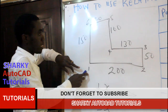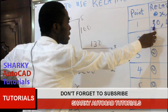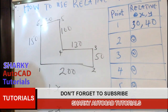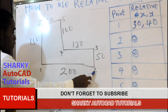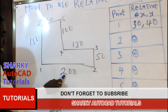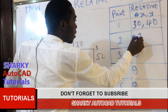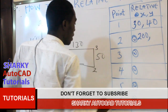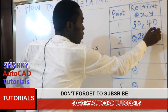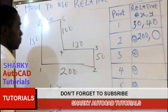Don't forget the starting point is given to you, that is 30, 40. It means 30 is the x-axis and 40 is the y-axis. Now, at point 2, we are using the original dimension, and the direction is what? Positive x, and the distance is 200. So over here, you write 200. And then you don't have y, so y is 0. Remember the coordinates that you don't have, you write 0 there.